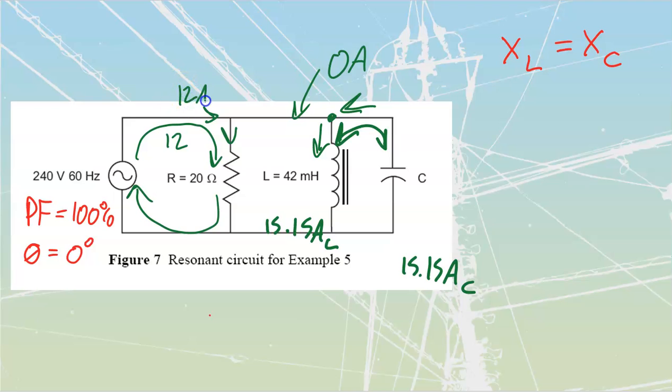If I take a look at this one over here as well, I see that I'm going to have 12 amps entering. I'm going to have 12 amps going through the load. Once again, Kirchhoff's law of current states that if all the current that enters leaves here, then this thing must be 0 amps as well. We see it reinforced over here on this supply end. So during operation, there is going to be 0 amps.